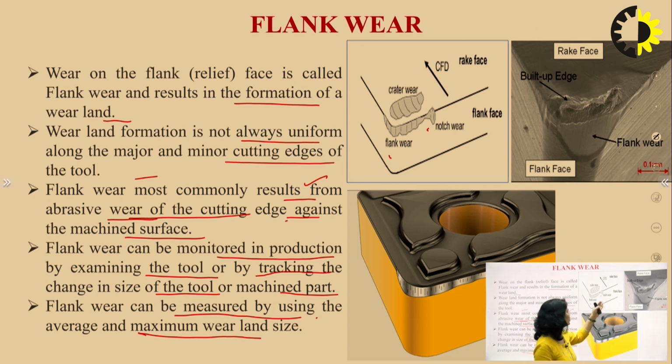This is the notch wear. Okay, so these are the, you can see the flank wear along the vertical surface. This is a built up edge formation. मतलब after the workpiece material is reformed, it is depositing on the cutting edge. Okay, और tip of the tool पे ये deposit होना शुरू हो गया है और यहाँ पे इसने built up edge की formation कर दी है. ठीक है, so it will act as the false cutting edge.